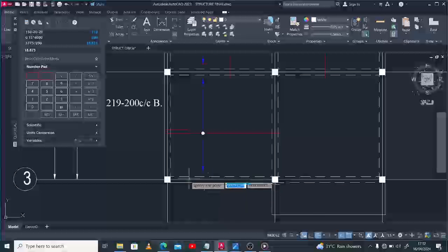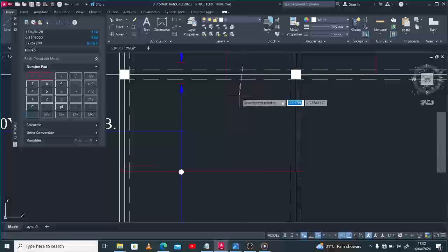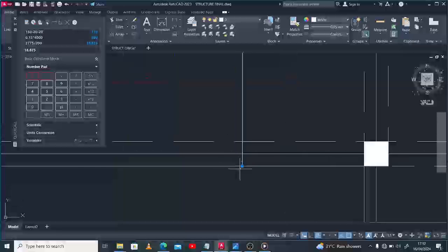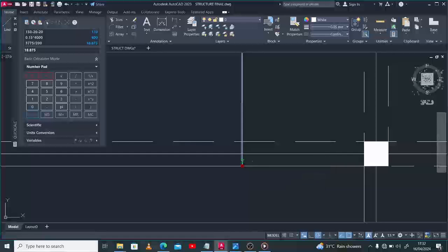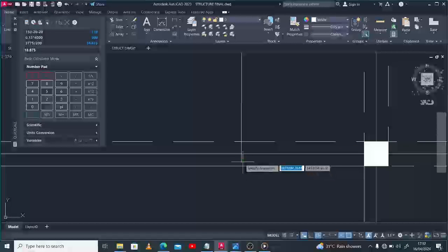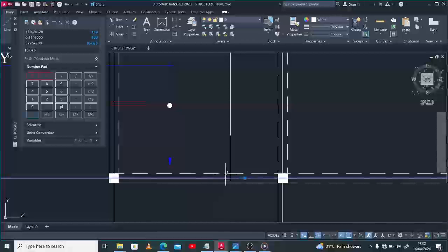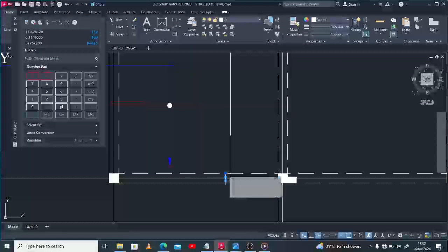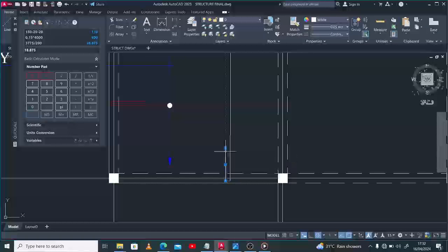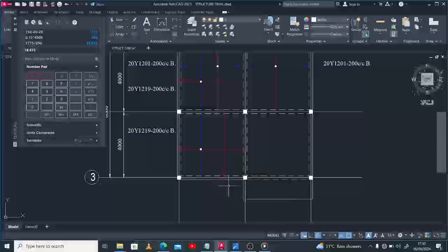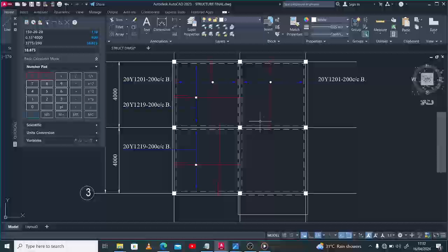How do I mean? This is the restrained end support on this side. So if our reinforcement spans to this place, for example, you have to just maintain a cover on this side, a cover of 20 mm, then the anchorage length, as I explained earlier in this video, of 110. Then you have the return length, all right, the return length of 600. You see that now? So that is how it works.